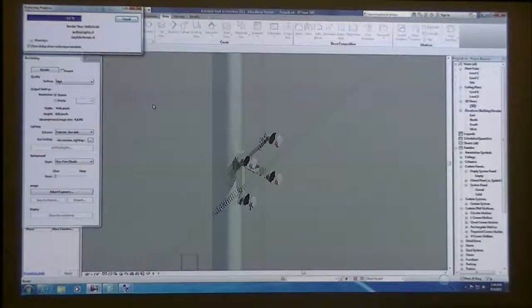So would that work on a complex surface? If you had a complex surface that is twisting and bending, remember this works great for a straight up and down wall. You would need to take this spider clip and bring it into a curtain panel pattern-based family and place it at the corners. And that might get a little complicated just because of the way that everything would twist and turn. You might start to see duplicate spider clips. But if you only put one spider clip on a corner, that'd probably work out pretty good, because from panel to panel, your glass isn't twisting that dramatically.